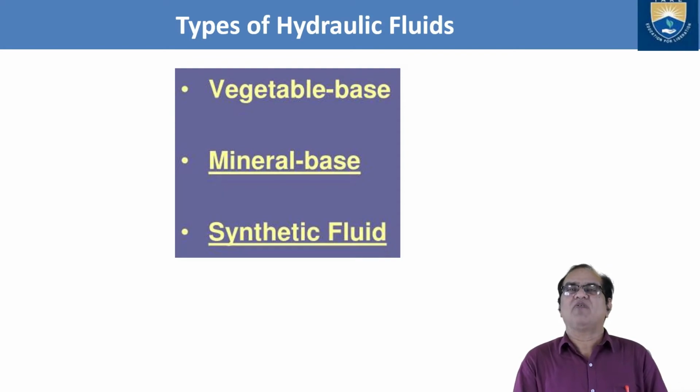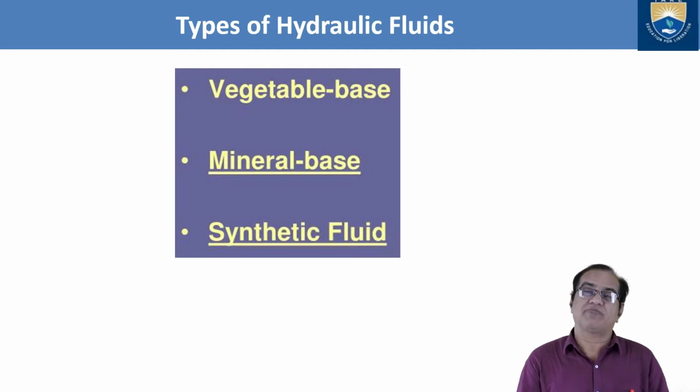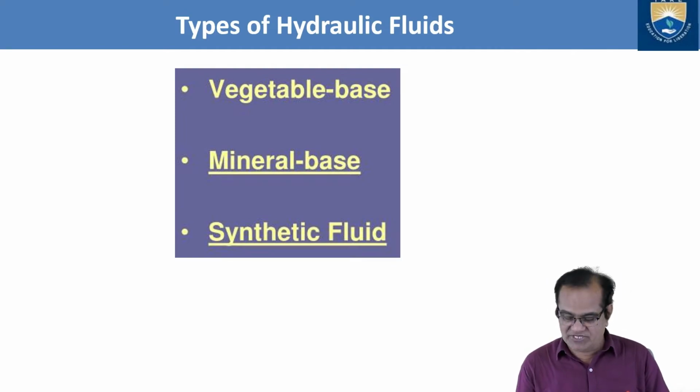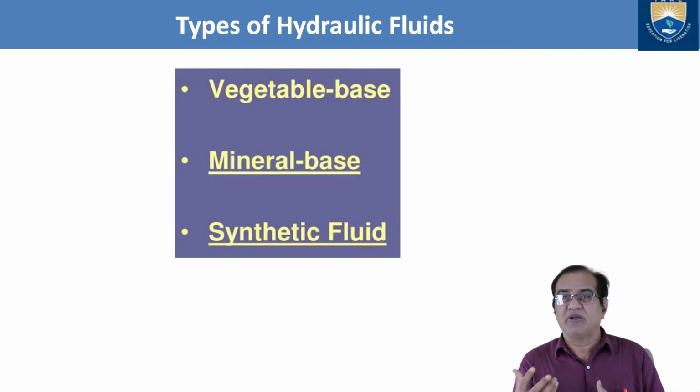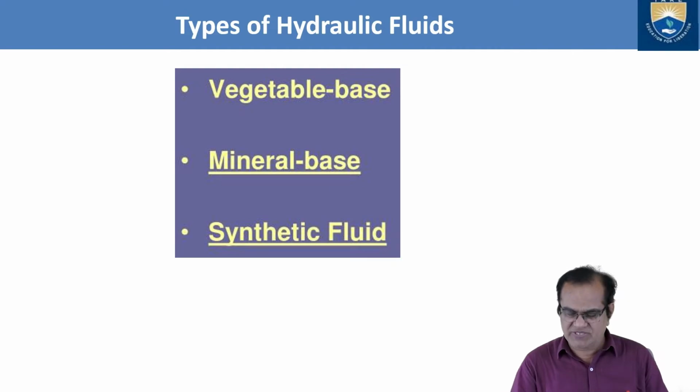However, each has some disadvantages. Mineral base is very good for low temperature, but synthetic fluids are not very good for low temperature. They are very good for high temperature, because mineral based are petroleum products, but synthetic fluids are not petroleum products. They are mixed with phosphate and other materials so that they become a lower fire risk.